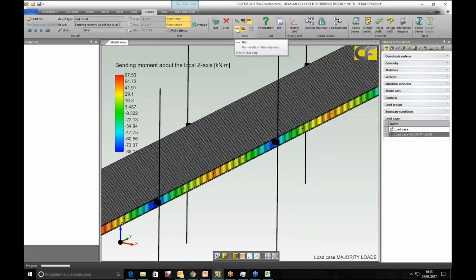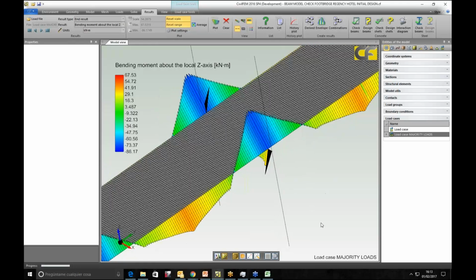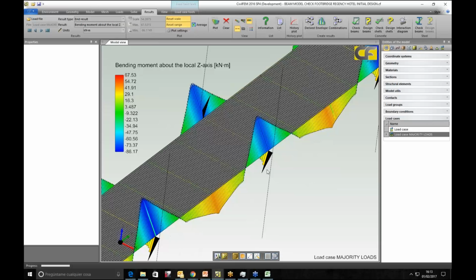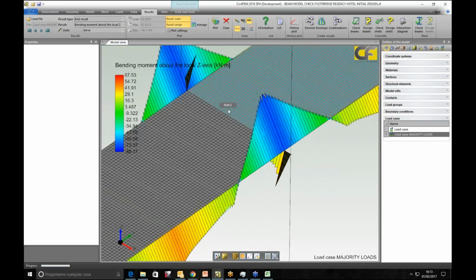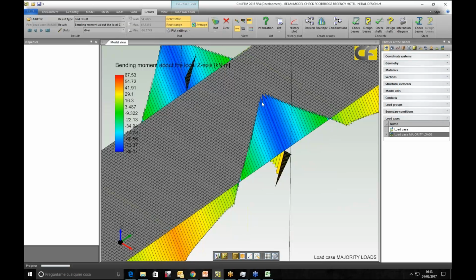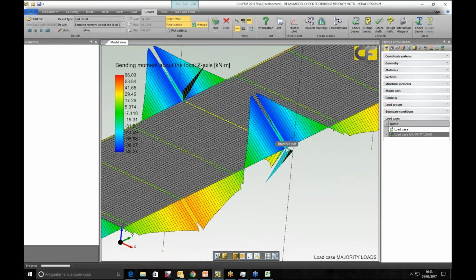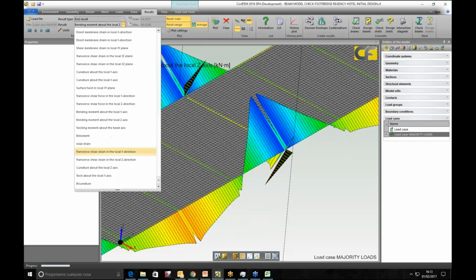But I think it's easier to see these bending moment loads with a thin option. I'm plotting it. These are the bending moments, negative and positive. These are the values we have. And we can see we have a small peak of forces here, and hopefully we should average the value for a constant variation. We can see we have a small peak at this connection, and we will also analyze the shear force.